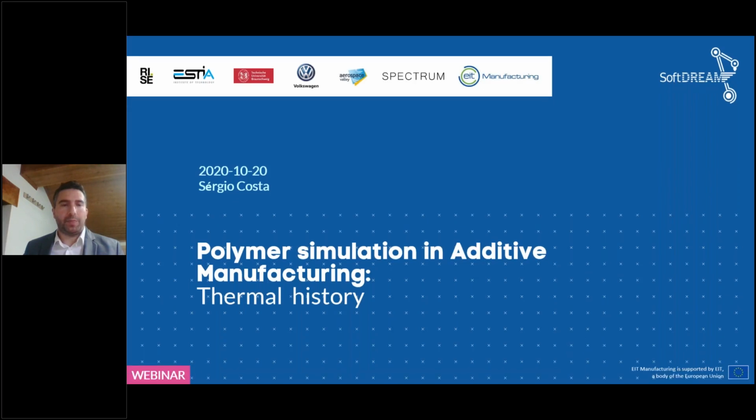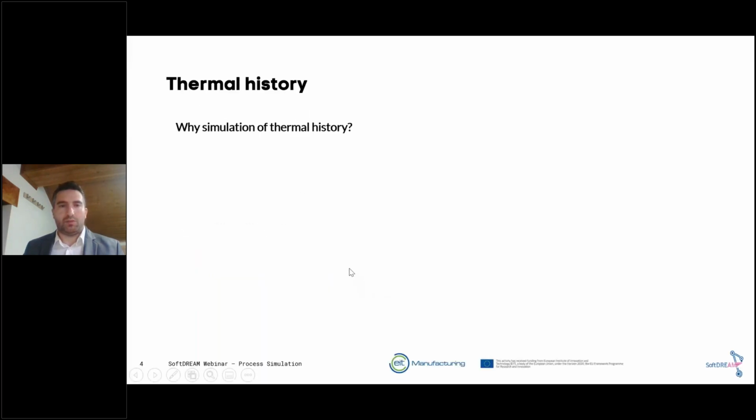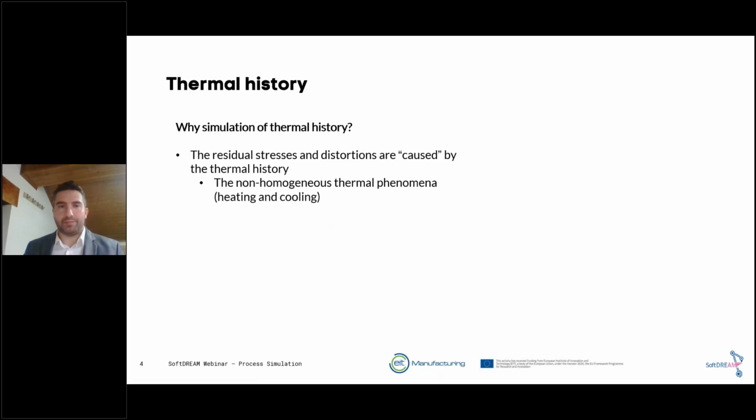Okay, so where to start? We start by simulating the thermal history. And why should we simulate the thermal history when we are interested in avoiding these defects and predicting the distortions? The reason is that the residual stresses and distortions are caused by the thermal history.